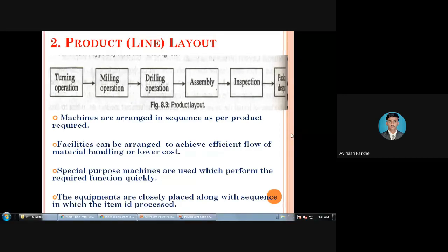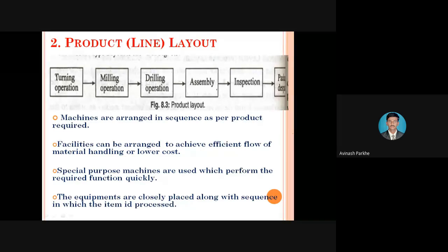Okay. So what is meant by that process layout? It is used whenever we have to go for batch production. In that case, we use the process layout or functional layout in the industries. What is the basic meaning of the process layout? Whatever similar types of machines are there, all those similar machines are grouped together. That means a number of milling machines are located at one location only. All the lathe machines, all the grinding machines, all the welding machines are located at one location only. And whatever production takes place, it takes place in the form of batches.